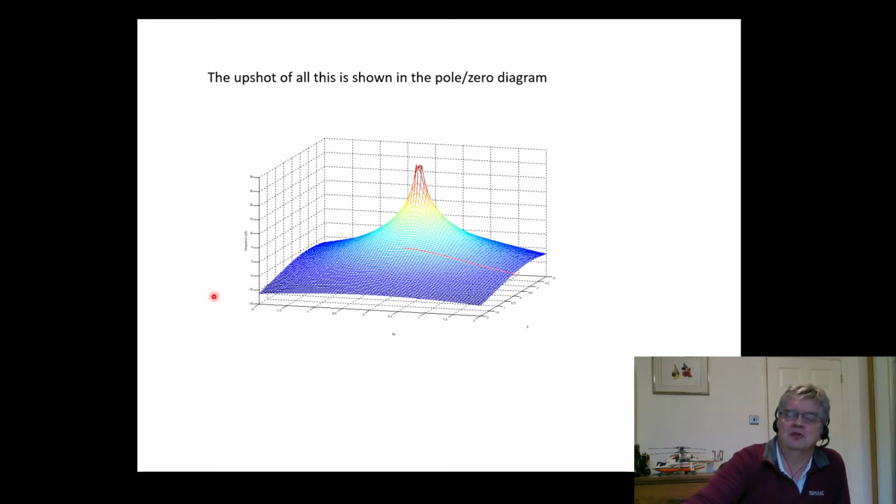And then we had a quick look at where we got to at the end of the last lecture. We had a look at this pole zero diagram for our passive filter, and it had the pole off axis, which means that they actually slice through sigma equals 0, so we can't see that that's sigma, but you should know that by now. We can see that we do not get an infinite response at 0 frequency, so this is 0 frequency, this is increasing frequency along here. And so this slice through the plane of sigma equals 0 gives us the steady state frequency response. And that's where we sort of got to.